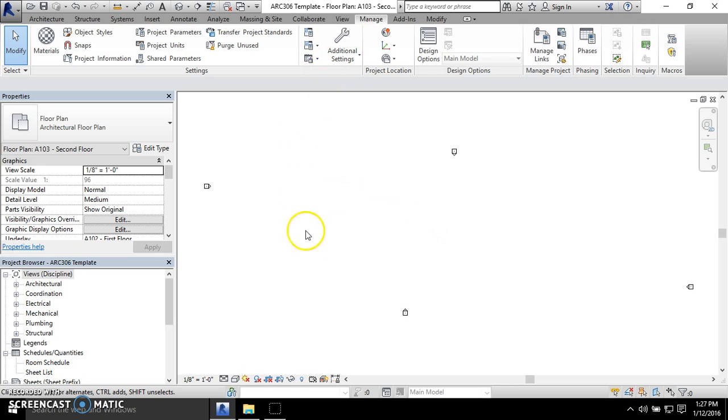For instance, if I had just a square building as an exterior wall, I can do a different design option for the interior. So I can do 3 different iterations of what the interior will look like, and just have one show at a time. So you have them all there, which is pretty new. That's something that's recently been added within the past year or two to Revit. So it's a nice little function.